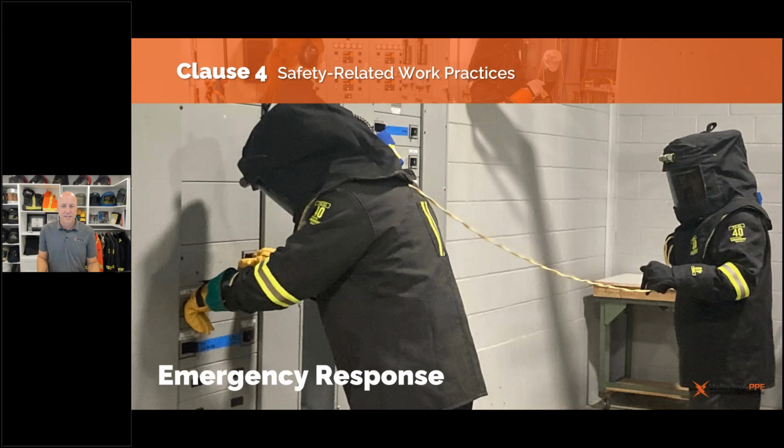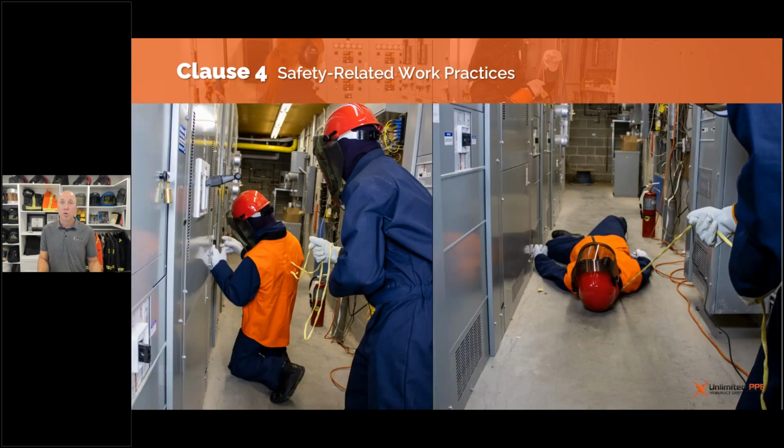So what has happened in the industry over the last few years? Production of an escape strap, which is an integrated accessory that can be built into your arc flash PPE, or it can be worn as a vest over top of your PPE. So if you have a small electrical room that doesn't allow for a 6-foot stick to be manipulated, or if you have a worker that's unconscious and you need to pull them out of harm's way, this is a great accessory to consider as a way to improve upon your emergency response plan as you then document this in your job safety planning.